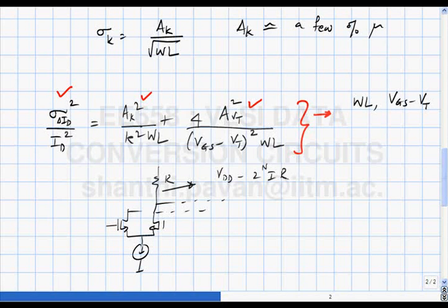So if VDD becomes small, clearly this voltage must be such that none of these devices below get into the triode region. If I reduce VDD, what can you say about the VGS, the overdrives available for all the transistors below? Becomes small. So when you have a small VDD, it basically means that you have to have larger sizes because the VGS minus VT available is limited. So you can make a sane choice.